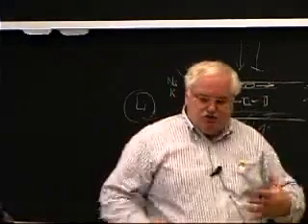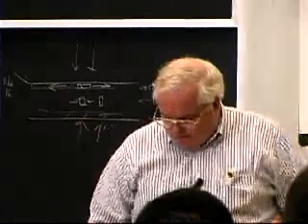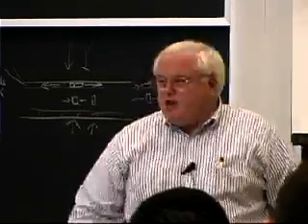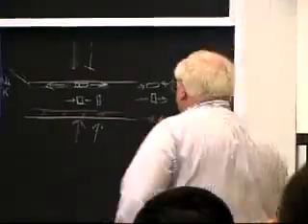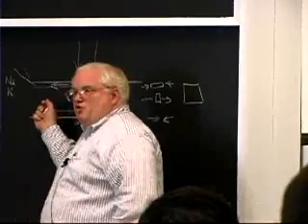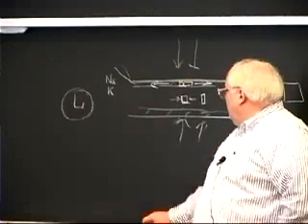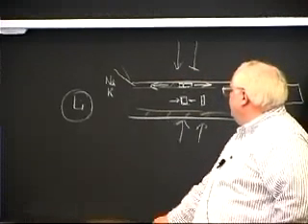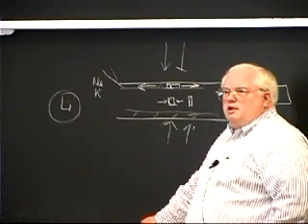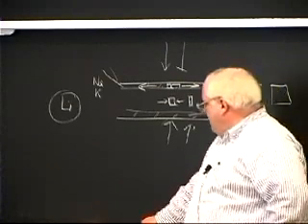So you're stretching the, it's not a lattice here, but you're compressing the bonds. So you can chemically temper or thermally temper glass and get favorable compressive stresses. That means that if you're going the other way, if the outside were hotter rather than cooler, you could end up with very unfavorable stresses, tensile residual stresses on the surface.